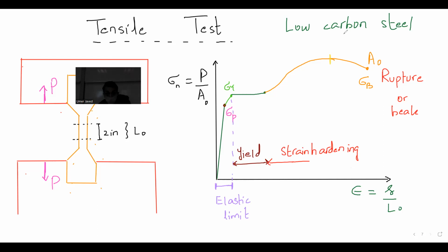Anyone want to explain necking quickly? When the diameter of this fellow, or the width of this fellow, decreases substantially, that's when the necking starts. And just so that I can explain this, this was your original fellow. With necking, it becomes like this.